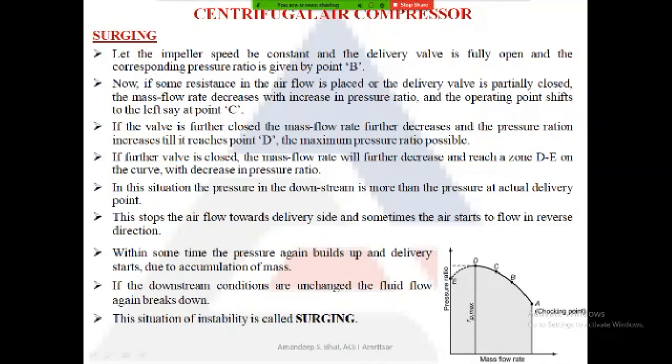After some time, as the impeller is moving, the pressure again starts to increase, and the air starts to get delivered into the delivery side. After some time, again the pressure on the delivery side increases, because of reduced mass flow rate, and the backflow of air starts to take place.